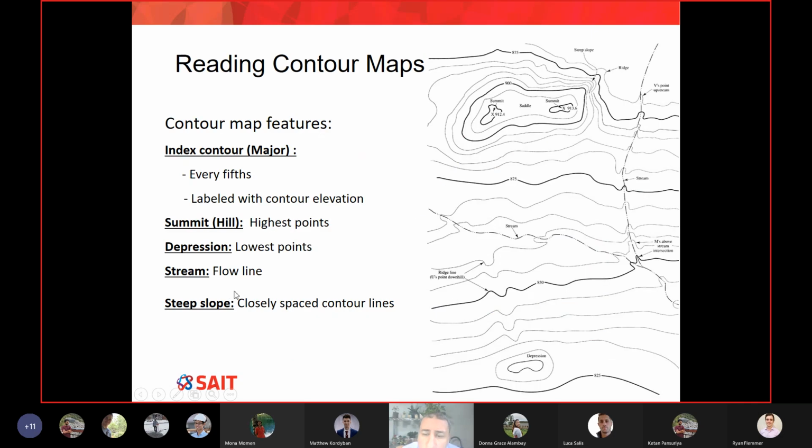I'm asking you, where in this whole map do you think has the highest slope? Where the dark line is? Look at this, please. I'm going to show you. Do we have the high slope here? Yes. You can see this is the area in your map that really has the highest slope. Why? Because simply look at this: all the contour lines are very close to each other.